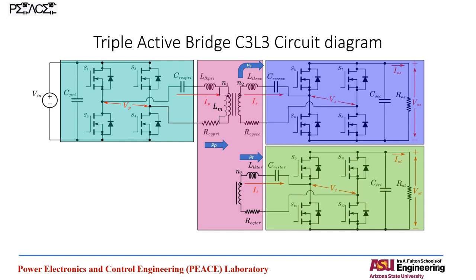If we have to draw an equivalent model of this circuit, we can replace the full bridges by a quasi square wave generating voltage source, and the resonant tank remains the same, but the inductors can be represented as impedances at different frequencies and harmonics. One more thing to note here is that the leakage of the transformer is being used as the resonant inductor, and the value of the resonant capacitor is chosen in order to achieve a certain value of the resonant frequency.